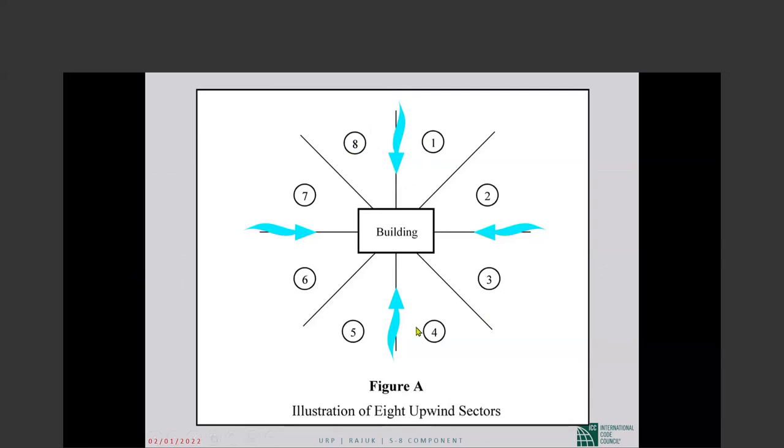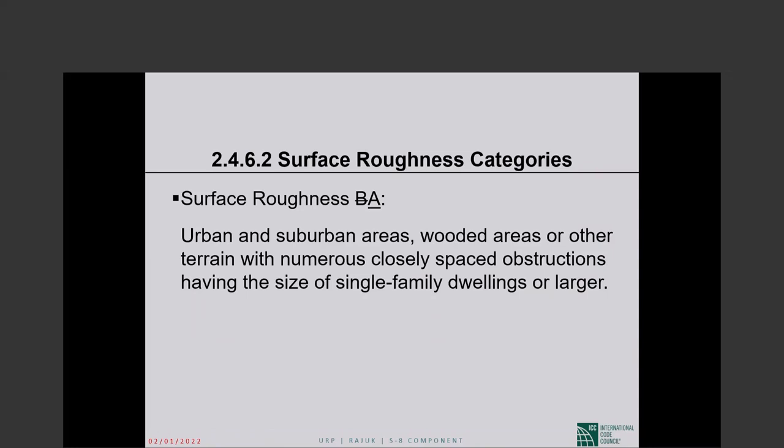If the direction of wind changes from up to down, then this will be the upwind direction. Then you will look at segments 4 and 5, and whichever has the rougher terrain will give you the roughness category for that face of the building or that direction of wind. Okay. So we have defined in BNBC AC7 roughness categories. In AC7 they are B, C, and D. In BNBC they are A, B, and C.